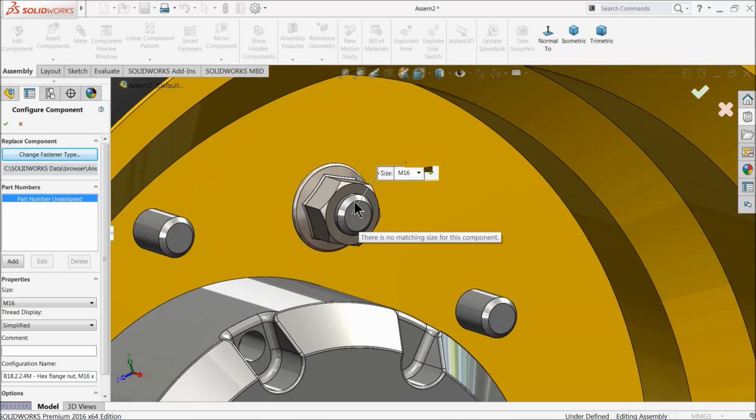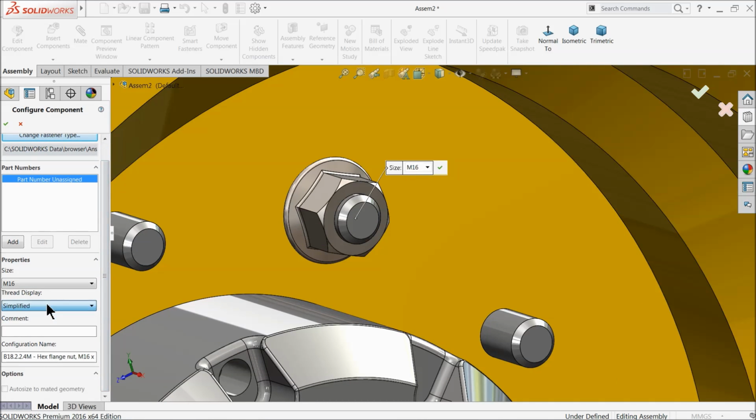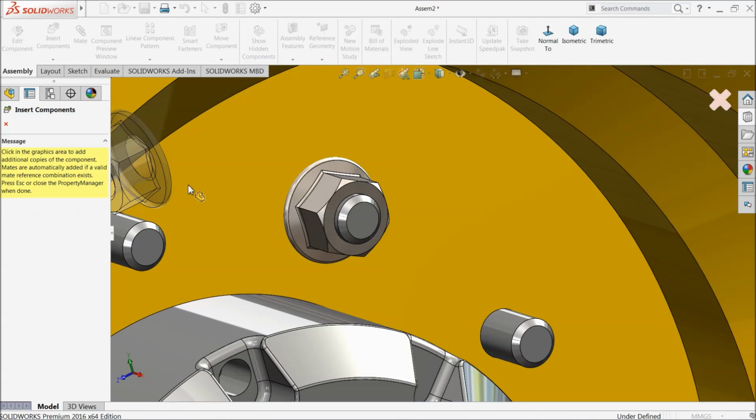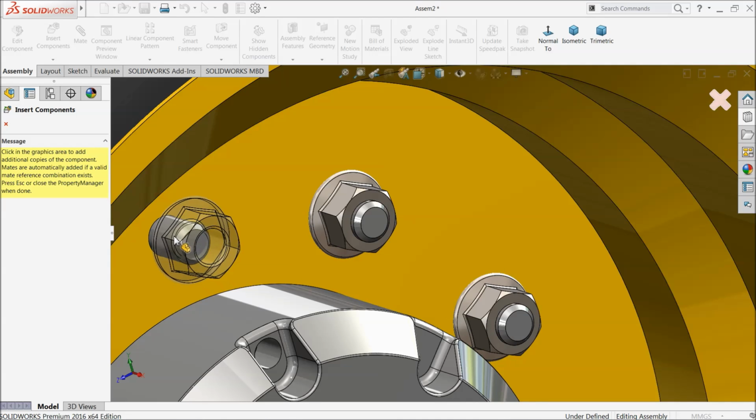Okay, M16, we need M16, no need for thread or anything. If you drag the nut to this extruded part, it will automatically fix. Just adjust a little, bring it here and go to the surface and it will automatically take the position. Okay, now it is again asking you, see, so I'll just take this and the surface. Okay, this one and the surface.